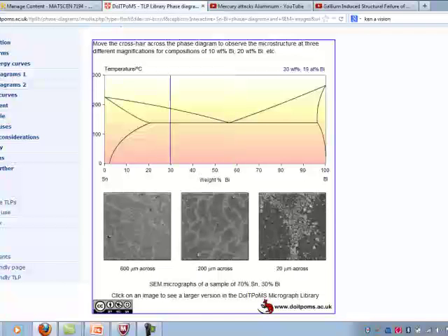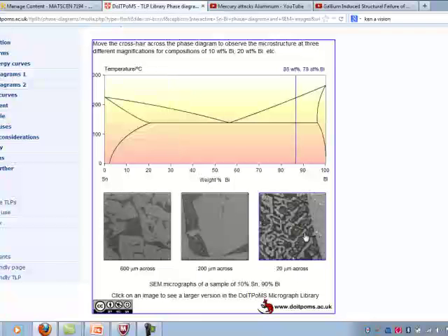Look somewhere in the middle of a hypoeutectic: these are regions where you have first primary solidification of tin, then bismuth solidification in a eutectic manner near the grain boundaries. Let's go hypereutectic over here. Here we've got big bismuth crystals that form first, and these are big enough you can almost see them by eye if you polish the sample, and then there's eutectic solidification inside of that.